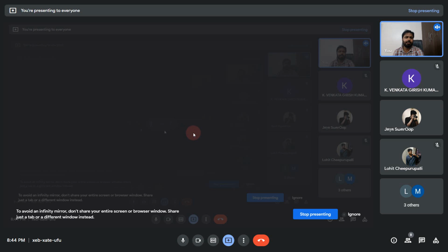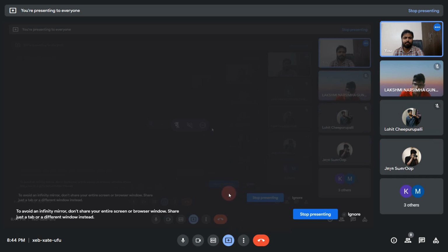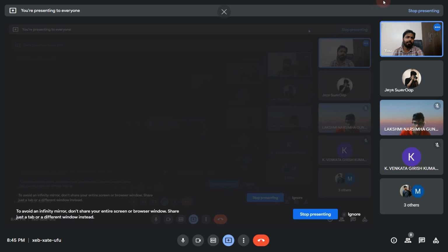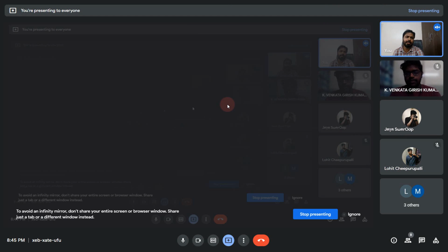Once you open your videos. So what is the catalyst that we use? The details we get is basically the catalyst components; different components are there. Basically zeolite based, we'll get a clay also. One binder will be there. Matrix will be there. It is a mixture of four components: zeolite, matrix, binder, clay. And details I will explain.